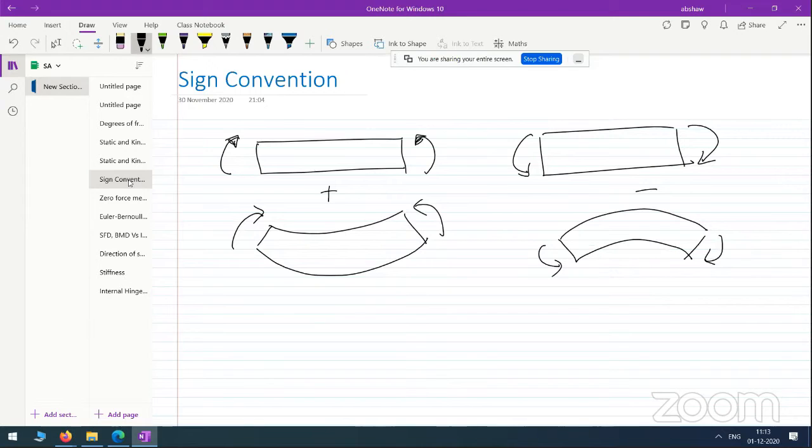So when you draw a bending moment diagram, that diagram needs to be drawn depending on whether the bending moment is sagging or hogging. By default, when we say bending moment is positive or negative, it means whether the bending moment is sagging bending moment or hogging bending moment. But when we use this bending moment in an algebraic equation, suppose we are adding or subtracting bending moments, then that algebraic operation needs to be performed based on whether the moments are in the same direction or opposite direction.